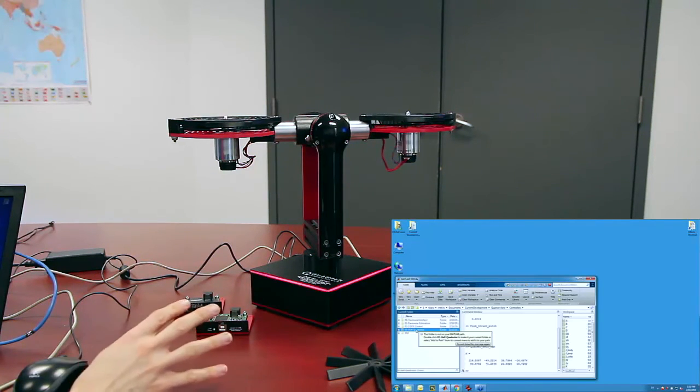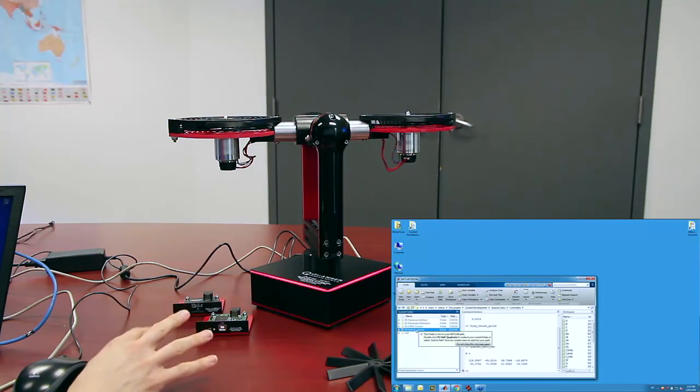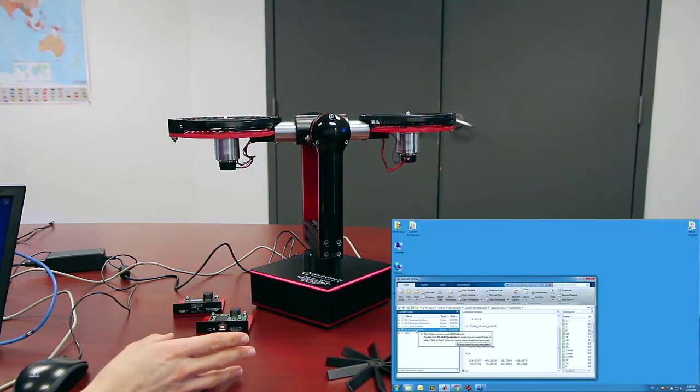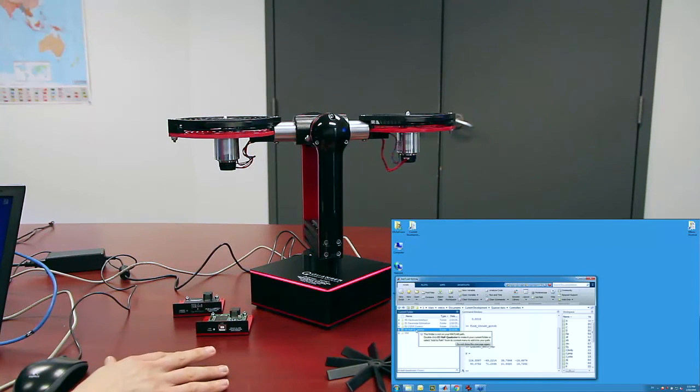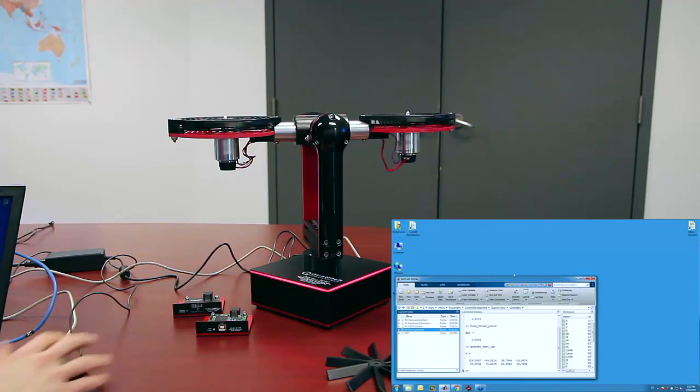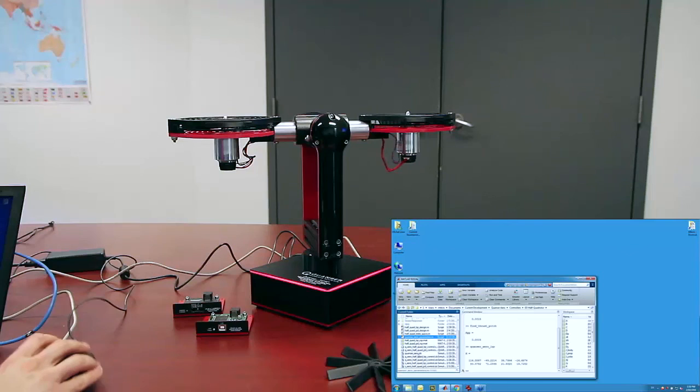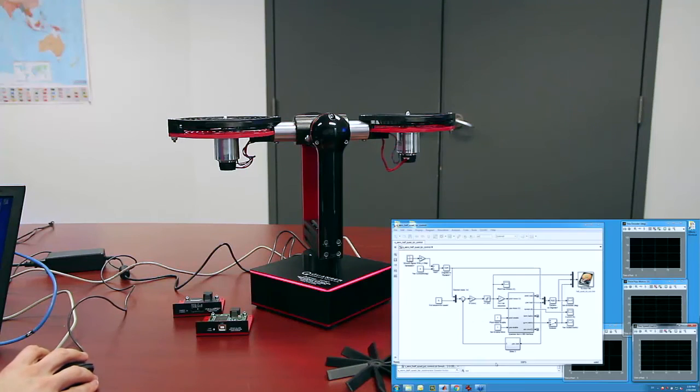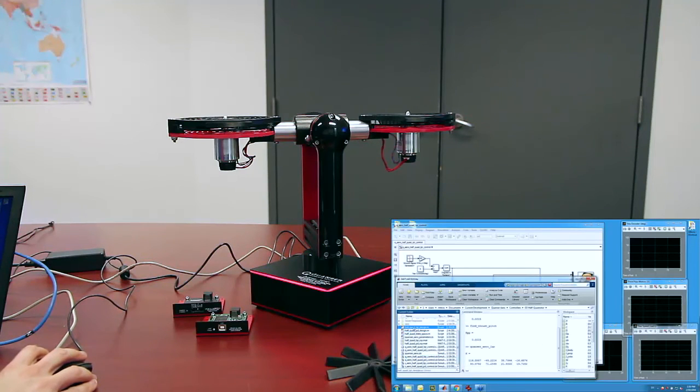So again, we developed the model for this, and we have two approaches: PID and state feedback using LQR. Also, we have a Kalman filter design to estimate the attitude of that. So let's go ahead and run that. I'm just going to go straight to the LQR design here. Again, we have a number of scripts that we supply.